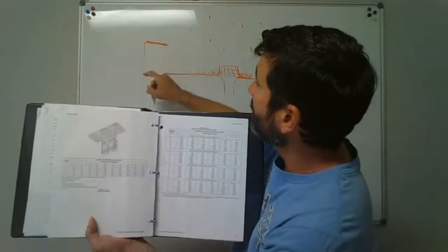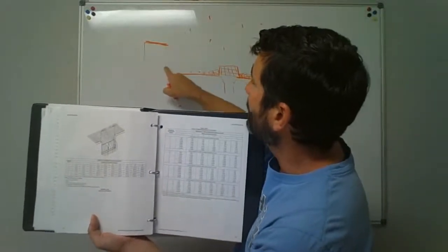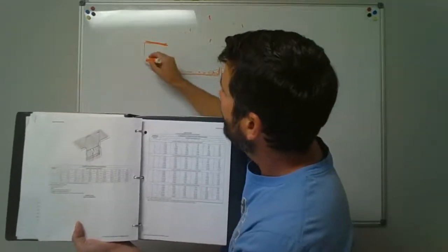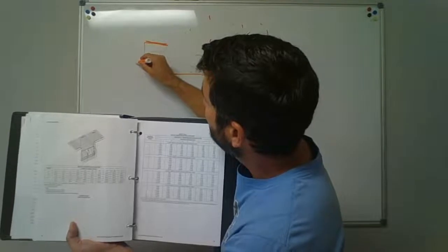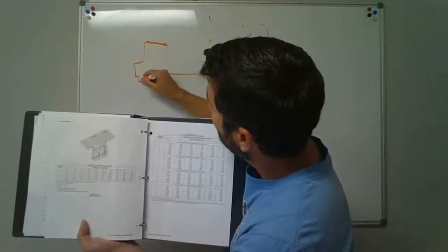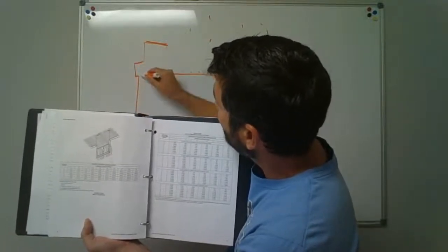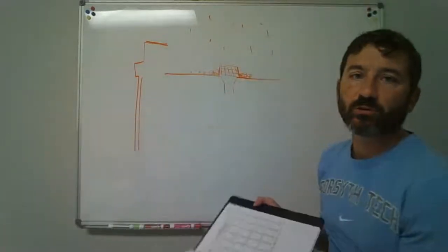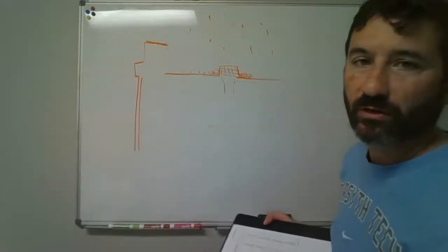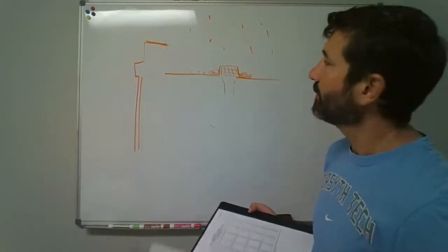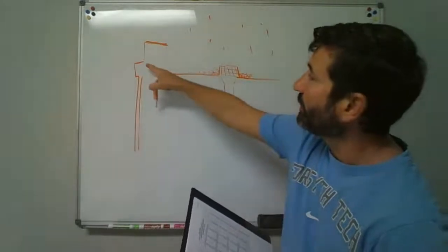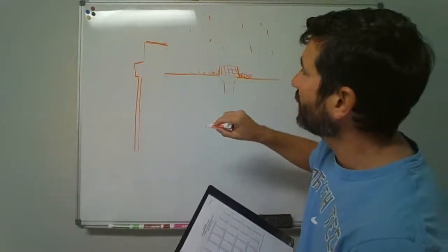You may also notice up there that they've got this place cut away, and you might see this cover come over it, and a storm drain pipe coming down the side. Look at some of your newer restaurants. Pull into a Taco Bell sometime. Just look up there. See how the roof is built up higher. Look and see if they've got some emergency drains on these.